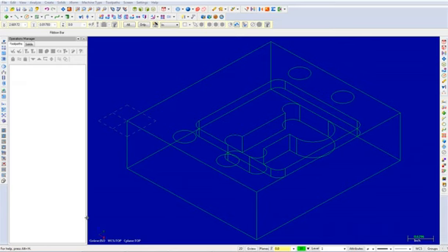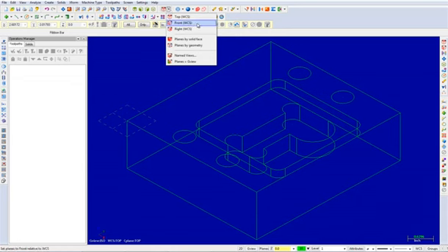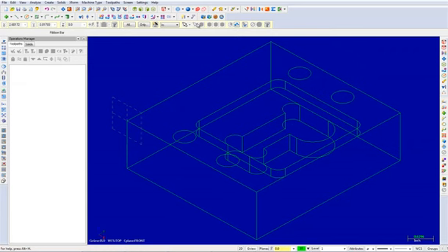Next, we will create circles on the front plane. In this step, you will change the construction plane to front and create circles. Select the drop-down arrow next to the construction plane. From the list, select Front. This will allow you to create geometry on the front of the part. Now choose the Front Graphics view.